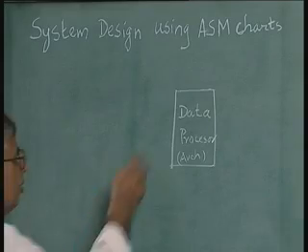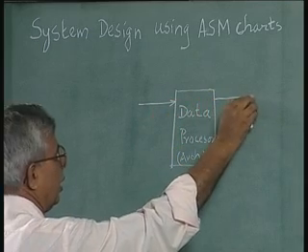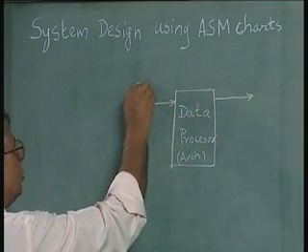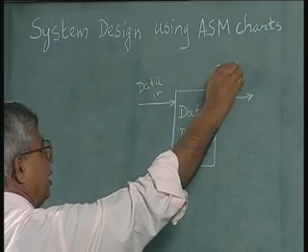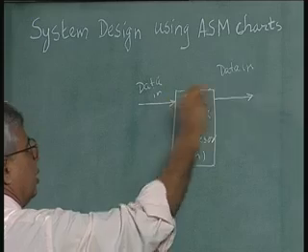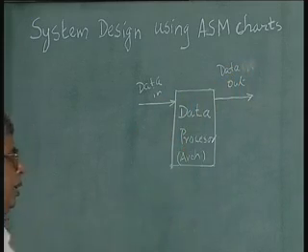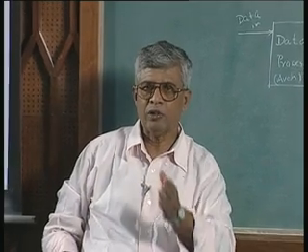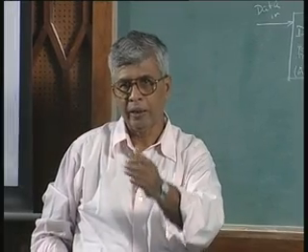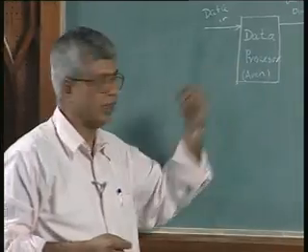So, the data processor will have inputs and outputs which are data in and data out. In the case of a multiplier, it could be x and y, the data in, and product of x and y could be data out. But as I said, how do you know when you start the multiplication? How do you know in what sequence you go over and multiply row by row? All that has to be provided to this functional block.